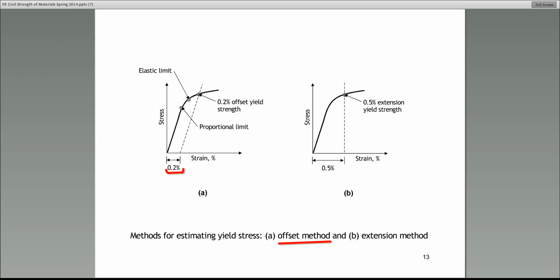when we develop their stress-strain curve, they do not exhibit a well-defined yield point. Remember I showed you the stress-strain curve for a ductile material, a typical steel, the one that we just looked at a few minutes ago. When you see that double kink and you could draw the horizontal line, you have a pretty good idea where the material will yield.